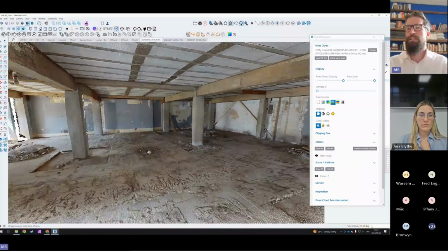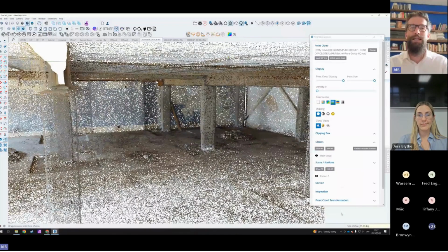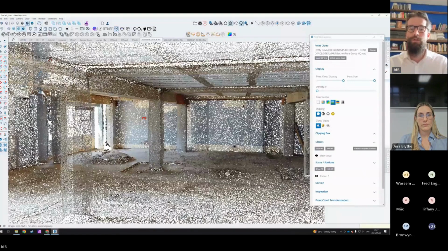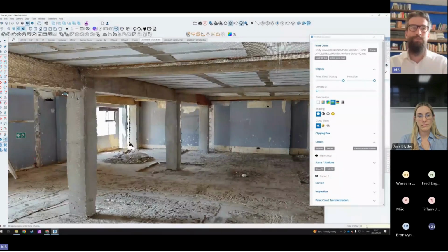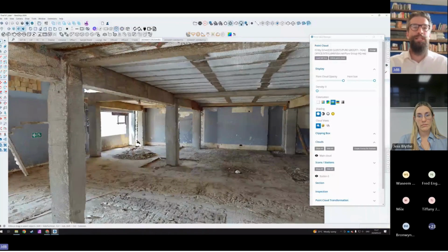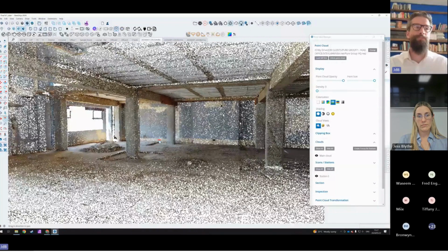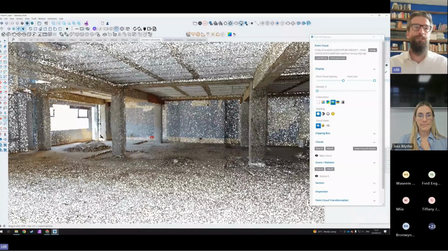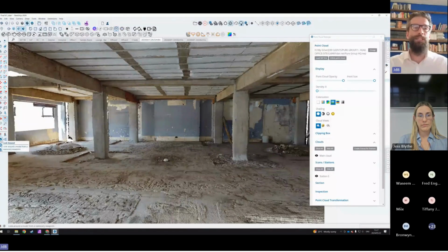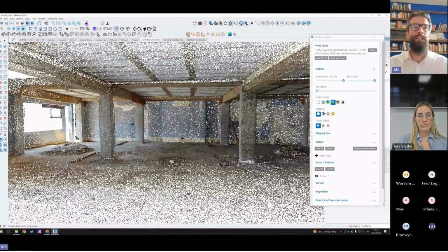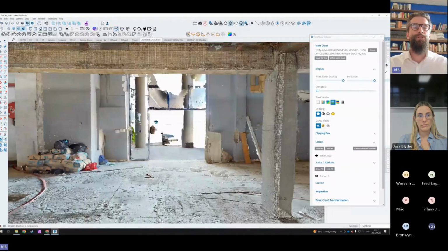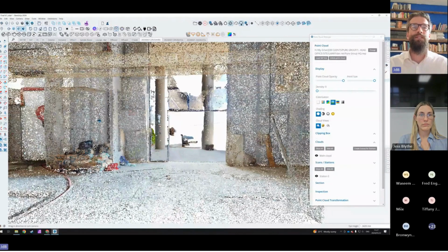Whereas normally in SketchUp Pro, your field of view is set up to 35 degrees, which feels almost like an isometric flat view. So just keep that in mind. You want a nice wide view when navigating a space. And then with the orbiting and the panning tool, you can navigate the space and even look around with the eye tool to see the space. So that's a great way to use a point cloud as both a surveying mechanism and as a presentation tool with your client.